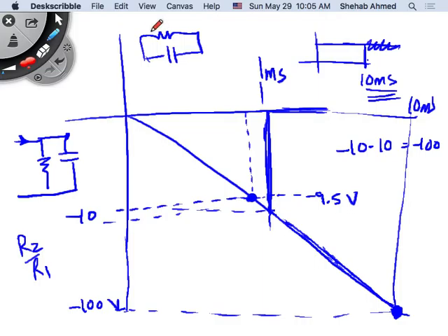Without the resistor, it fell. So the resistor was an open circuit. You have to always think that the resistor was there, but it was very, very large. Now I brought this resistor from infinite value to 1 mega ohm, which is still large. If it's infinite value, it will fall down to 0, like the case for the capacitor. If it's 1 mega ohm, instead of falling to 0 quickly, it will fall down with a certain time constant, exponentially.